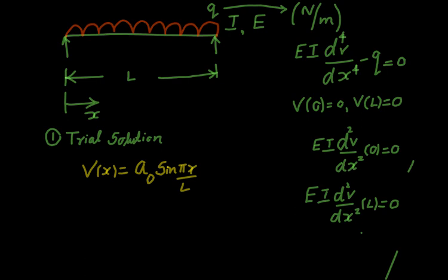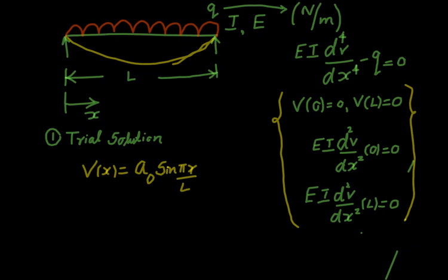We know the reason why we have to assume this particular trigonometric trial solution. First of all, the beam bends in a sinusoidal fashion. Okay, it sort of mimics a sine wave, so that makes sense. The next reason is that all these boundary conditions are readily, immediately satisfied by this particular trial solution. So we have got very good reason why we have to assume this particular trial solution. We know that it satisfies the boundary conditions. We have seen that in point collocation method. If you want to try, please try and check it through.